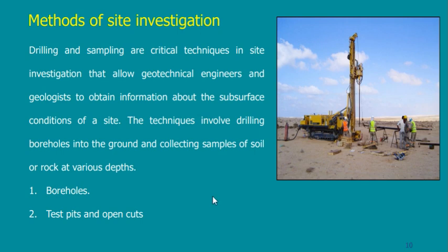But as you know, I need as much as possible to get the sample as it is in the ground. Suppose I have in the ground sand that is very loose. If I bring it up, and during bringing it up I just compress it, and then you give me the sample, I will look at the sample and tell you it is not loose, it is compacted. Because you've already compacted the sample to bring it from bottom to top.